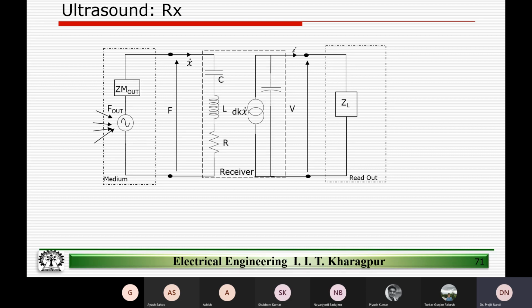See, we are doing everything in parts. First, based on the sound wave equations, we understood how the medium is going to behave and what will be the relation of the pressure and the displacement. When we studied the medium, we looked at the relation between the pressure at a particular location x and the particle displacement, and the fundamental relation relating pressure, particle displacement, or velocity. We looked at that, right? And then we talked of acoustic impedance.